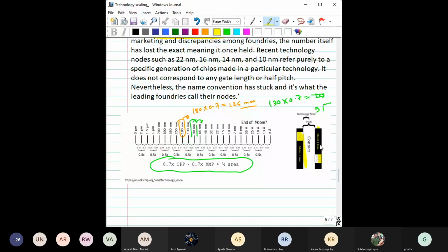Now, this MOSFET has to be connected with another MOSFET. How do you connect it? You have to take a type of flyover, an overbridge, right? Go to another height, make a bridge from here, go there, put it there. That becomes metal layer 2. Like that, in current manufacturing technology, at least 7 to 8 metal layers are there, one after another.